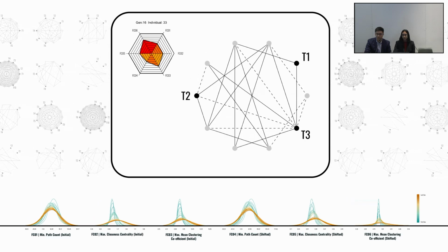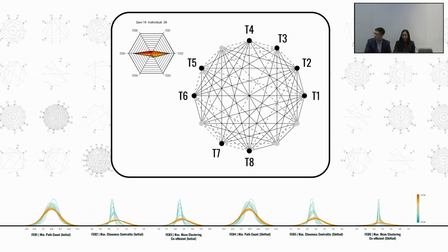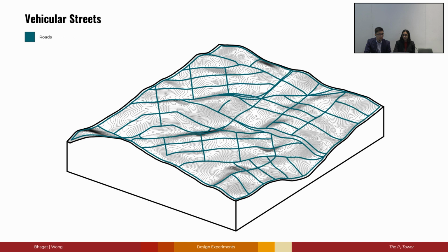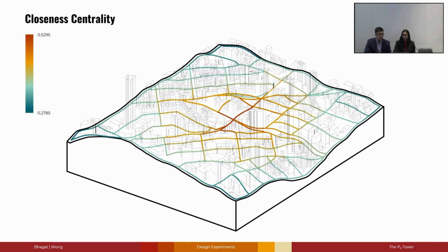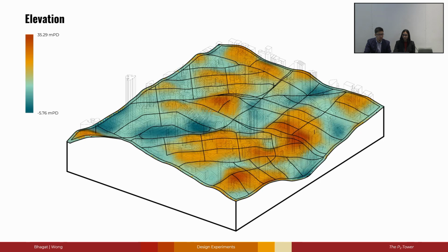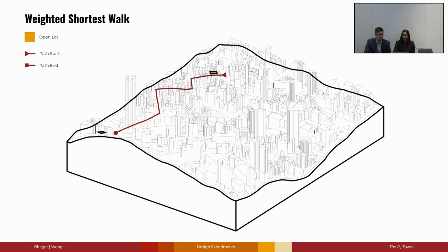However, we cannot simply superimpose these graphs on complex urban environments in Hong Kong. Therefore, we employed a weighted shortest path algorithm to translate these connections into context-specific architectural corridors. By analyzing Hong Kong's open source data for the city, we used 5 weightings: closeness centrality, daylighting hours, distance, visibility, and elevation to weight the algorithm and create context-oriented connections between multiple towers.